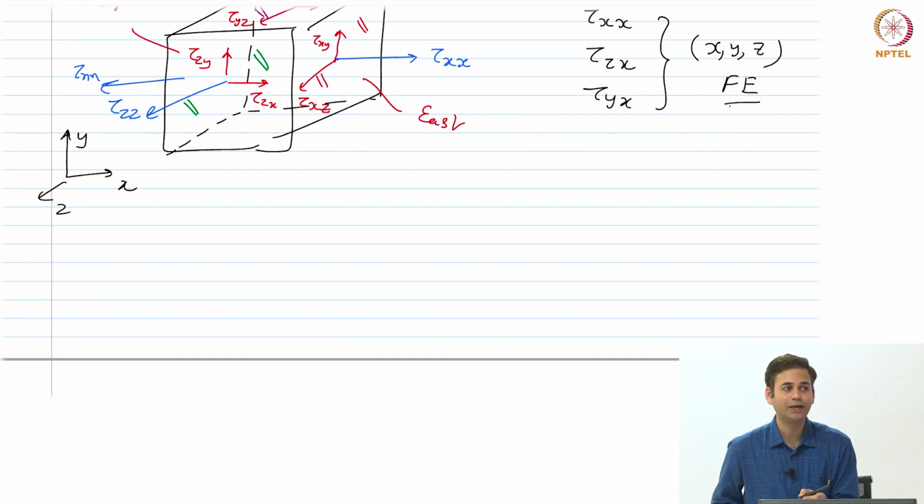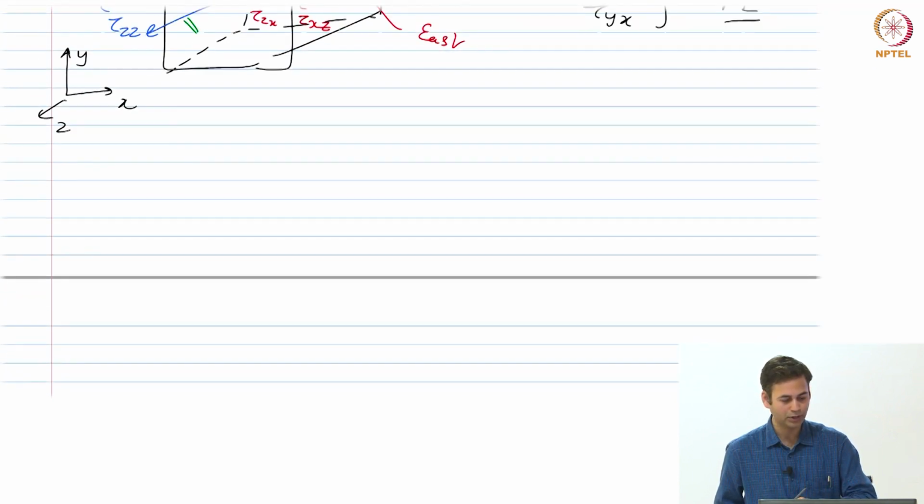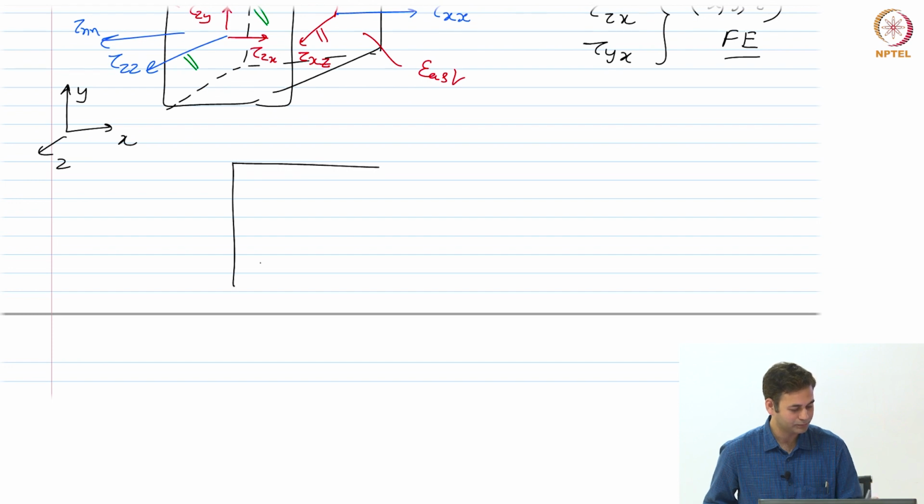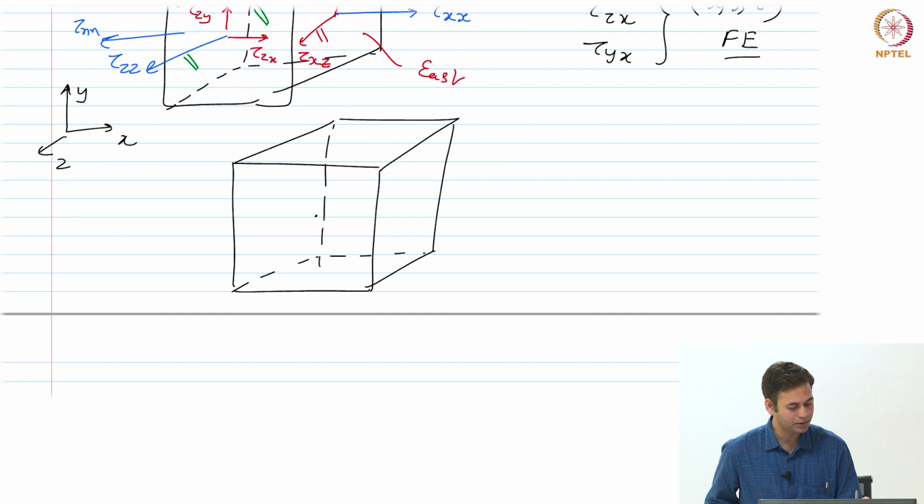Now, we have to again use Taylor series expansion if we were to draw them on the fluid element faces. Here, only to represent the state of stress, I have drawn it on the surfaces, but I will go back to my original fluid element that we have used in the definition of the conservation of mass. So I am redrawing this figure with our original way, where the properties are all defined at the centroid. This is the centroid, xyz, and I have tau xx defined at the centroid of this fluid element.